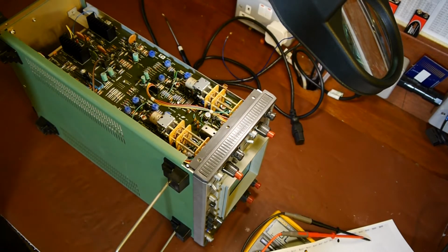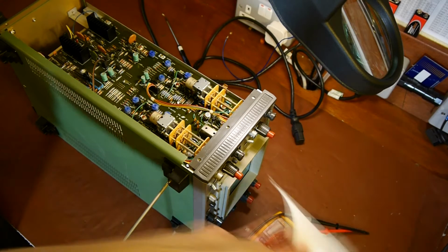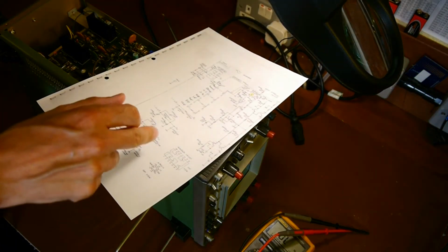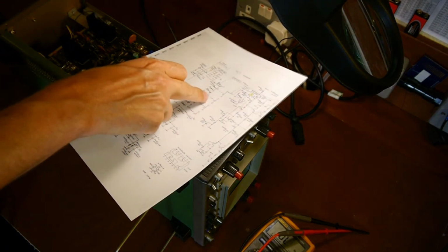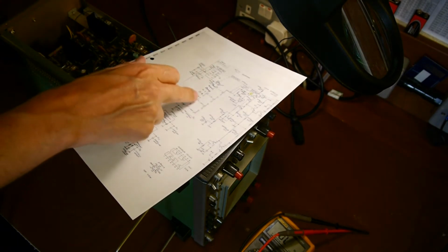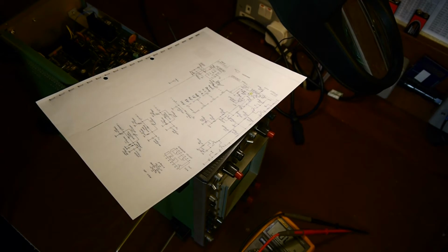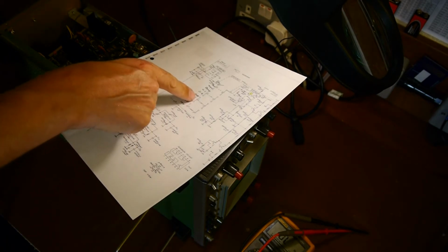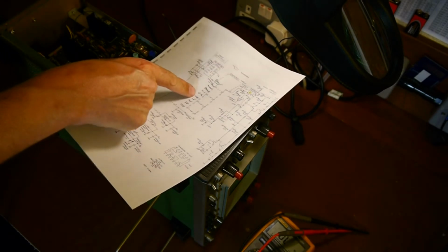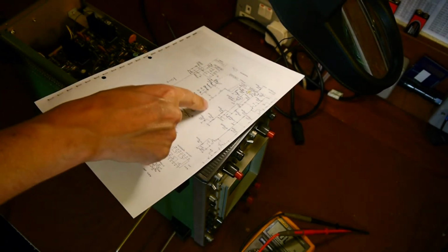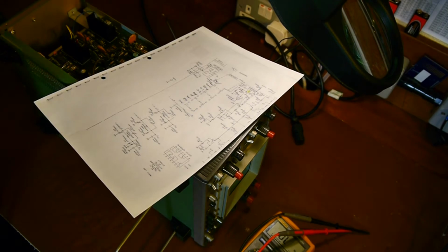So yeah, it's not the capacitor shorting it out. I was really expecting that to be the problem. It doesn't mean there isn't a problem with this attenuator switch, because it could still be a problem with the switch, because obviously we have to switch through this circuit, don't we? So it could be that either the wiper on this side of the circuit is open, or the wiper connection on that side is open.